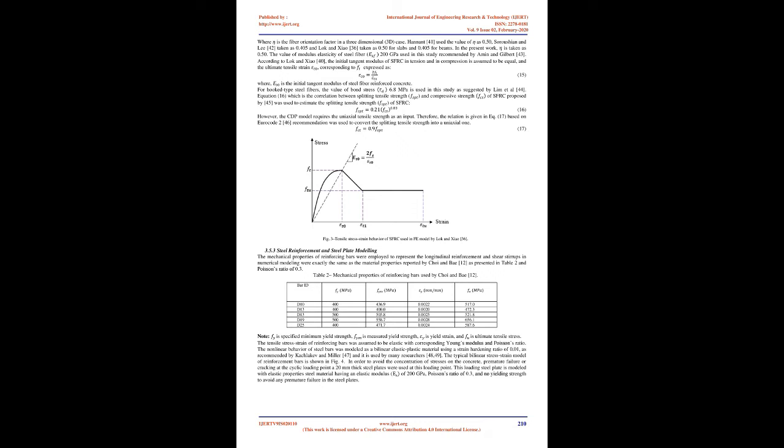3.4 Analysis approach. Nonlinear finite element analysis of the beam column joint specimens was performed in ABAQUS/Standard by considering both geometric and material nonlinearities with viscous regularization. In the static general analysis procedure of structural components, an appropriate solution algorithm is needed to solve the nonlinear equations. Newton-Raphson equilibrium iteration provides convergence at the end of each load increment with tolerance limits for all degrees of freedom in the model 18,19. Automatic increment with a large number of increments and a small time step size are used to improve the convergence rate.